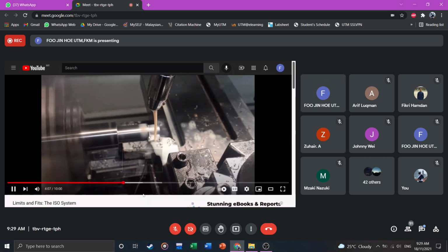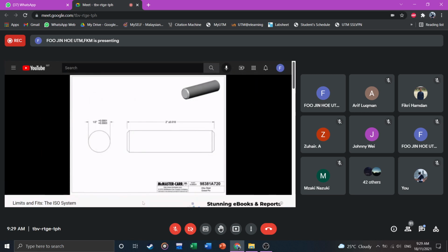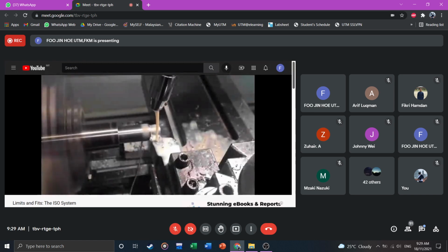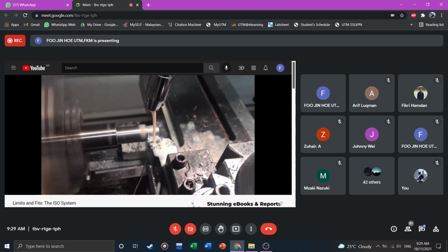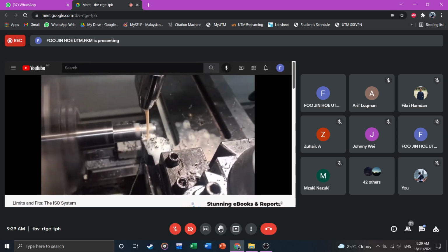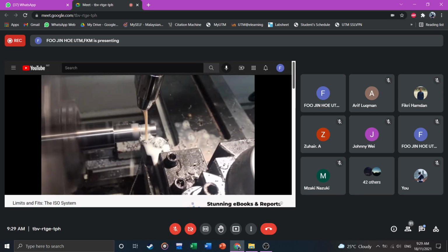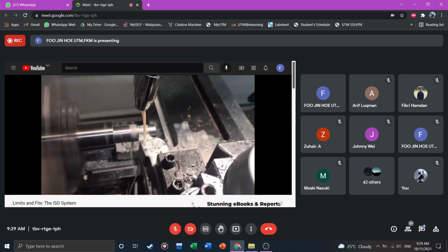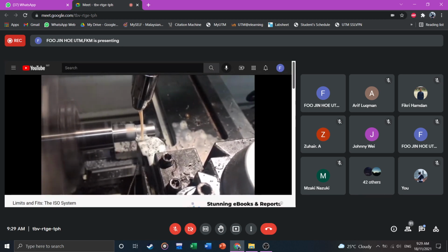Is on each size of dowel pin, but it would be cumbersome to have to create engineering drawings for each size. So instead, you can just say the tolerance will always be a bit over the specified dimension, where a bit over scales roughly proportionally to the target size. We could say that all the pins will be between 0.1 and 0.3% larger than the nominal dimension. The problem is we don't want people to have to constantly calculate what these percentages are.